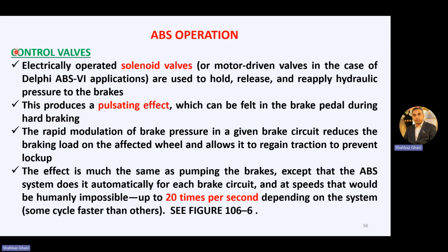Then the control valves: electrically operated solenoid valves, or motor-driven valves in the case of Delphi ABS6 applications, are used to hold, release, and reapply hydraulic pressure to the brakes. This produces a pulsating effect.